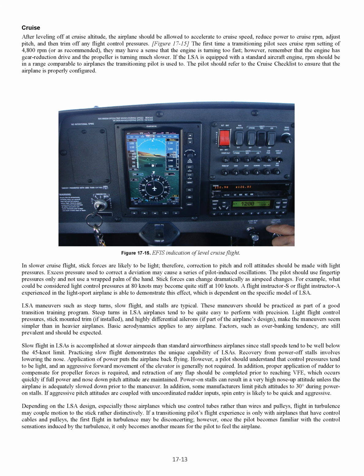However, a pilot should understand that control pressures tend to be light, and an aggressive forward movement of the elevator is generally not required. In addition, proper application of rudder to compensate for propeller forces is required, and retraction of any flaps should be completed prior to reaching VFE, which occurs quickly if full power and nose-down pitch attitude are maintained.